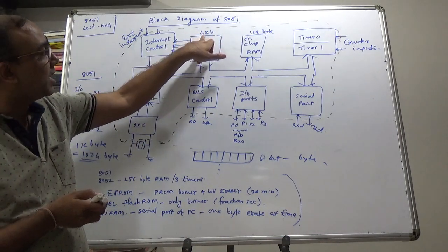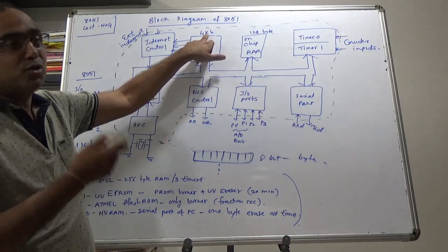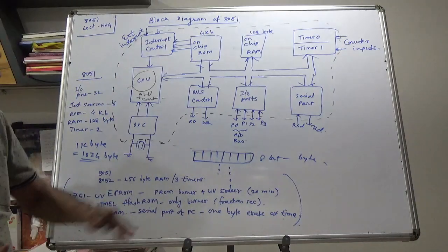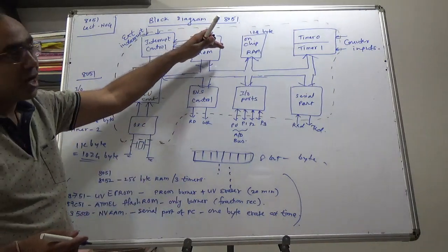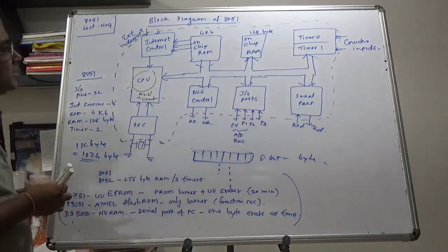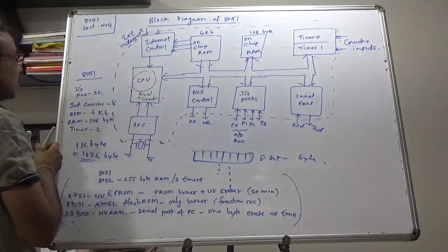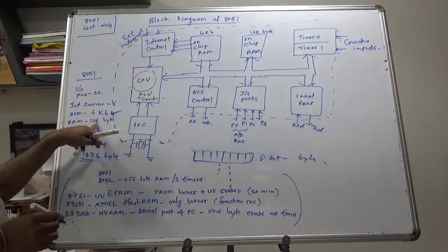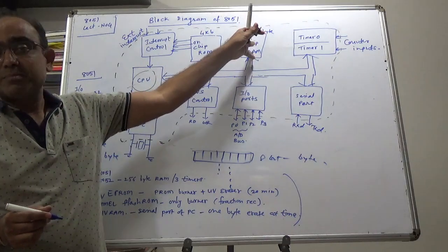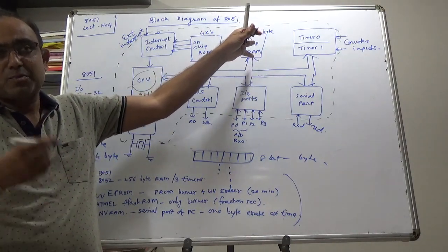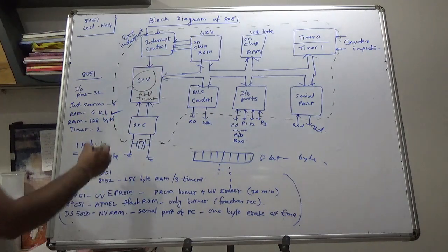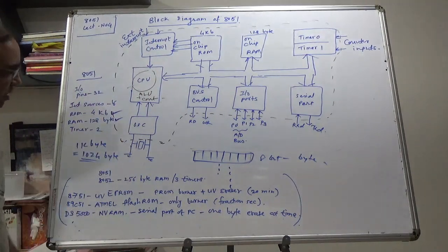So that's why I have written here 4K. So 4000 bytes. So this way, these are the bytes. Consecutive bytes will be there where we can store our program, permanent data, and so on. We'll discuss that in the coming lectures. So this size is here, 4 kilobyte. Then why is RAM needed? Because every time you don't need permanent storage, sometimes you need some temporary storage of data while your program executes. For example, you may need a stack memory. So that will be here in the 128 bytes.